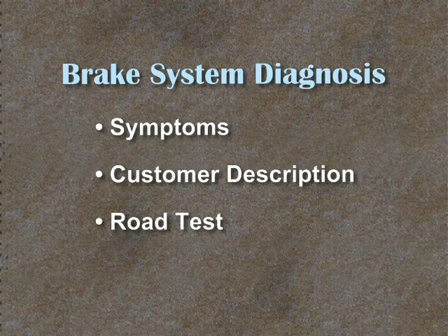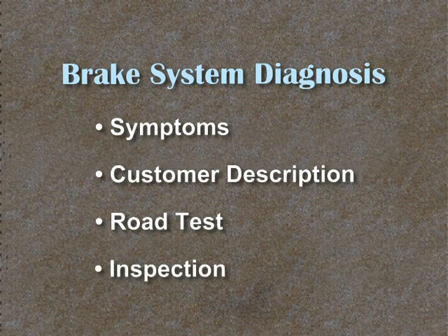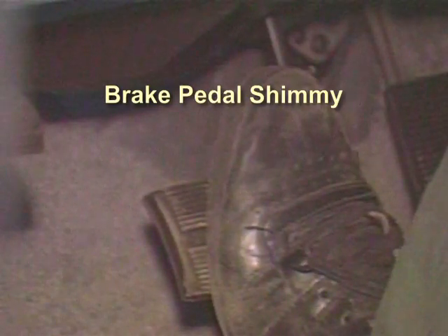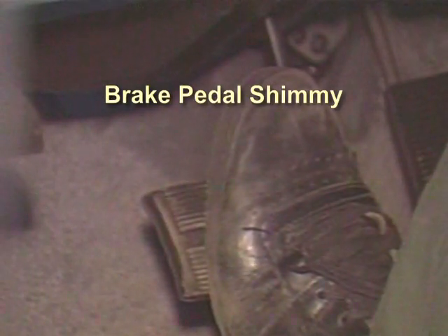If not unsafe to drive, road test the vehicle to verify the trouble. Then, inspect the brake system to pinpoint the exact sources of problems. You will then be prepared to decide what must be done. For example, brake pedal shimmy is a very common problem.